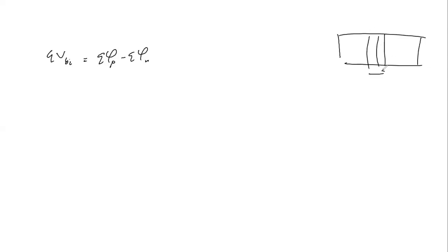We are able to have this depletion region for the P and N-type material. So the barrier potential is what we're trying to figure out this time. And once we have this, we already know that the energy, E sub I minus E sub F, is the same as Q VBI.